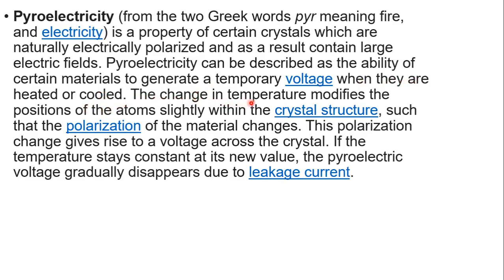The change in temperature modifies the position of the atoms slightly within the crystal structure such that the polarization of the material changes. This polarization change gives rise to a voltage across the crystal. If the temperature stays constant at its new value, the pyroelectric voltage gradually disappears due to leakage current.